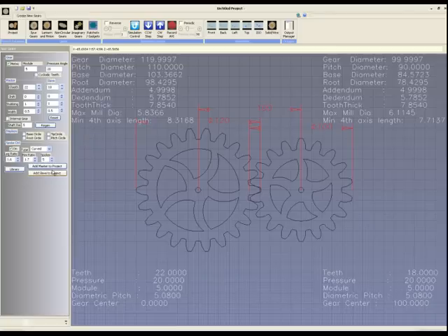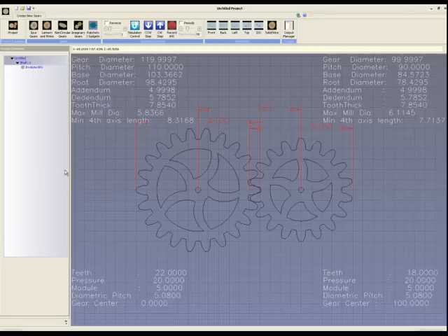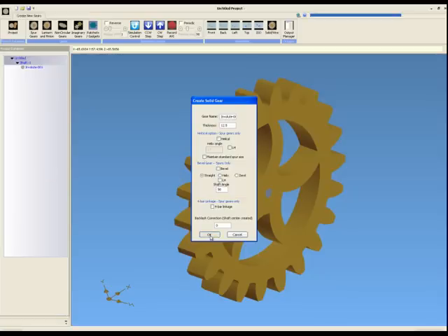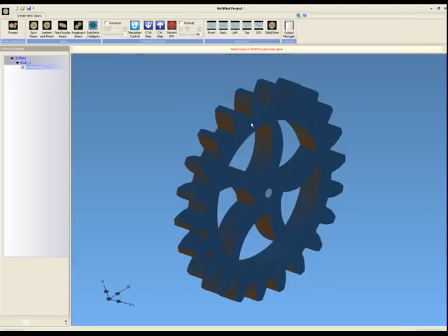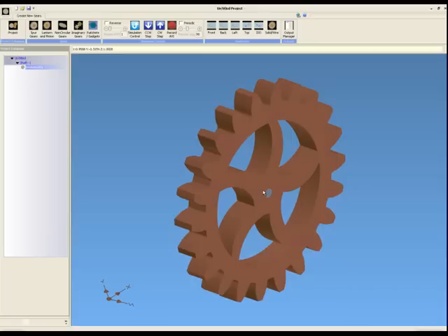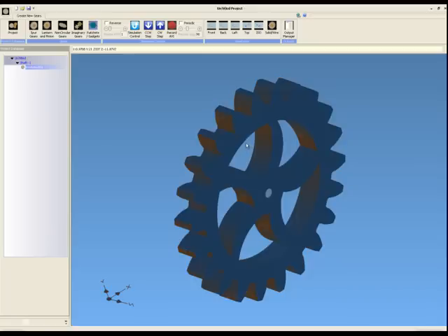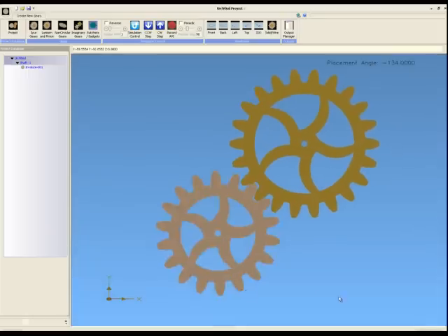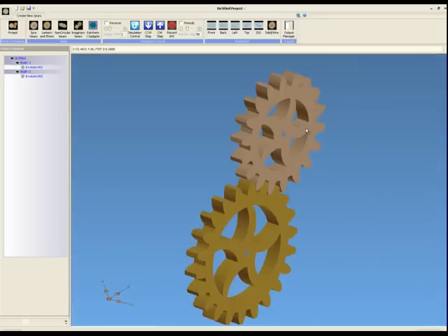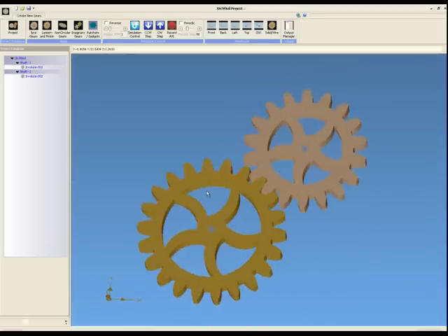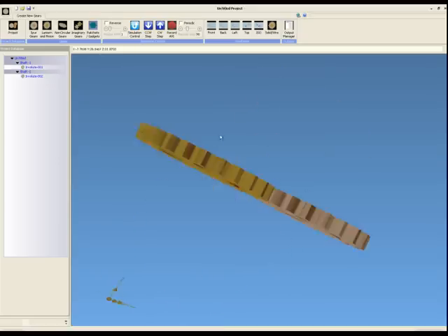So let's go back to the Spur creation and add a slave to this. And we'll just hit OK because we're not interested in any other type of gear at the moment than the Spur gear itself. We now have a screen, and if you've watched the project video, you know that if the gear is blue, we're going to place the gear on the outside of this primary master. And if we point to the center of the gear, it'll turn pinkish, and that tells us we're going to place the gear on a shaft. Should we choose to place it on the gear, we can rotate the gear around and stick it in a point in space. The screen then switches to an ISO screen view, and again you can rotate it around and go from there.